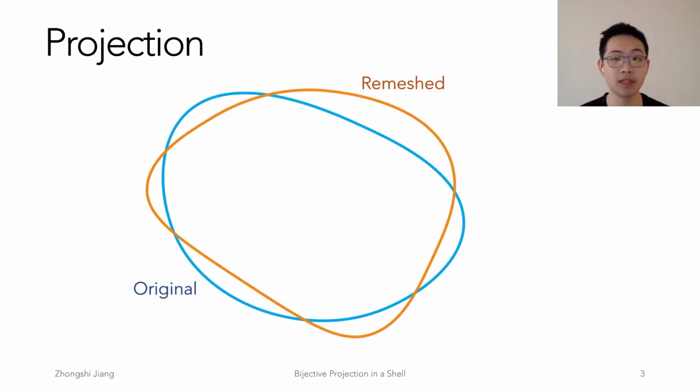The meshes approximate the same shape, so they should be close by in space. Therefore, our first attempt is to perform a closest point query. For each point on the original mesh, find which point is the closest on the new one. For smooth surfaces, this corresponds to Euclidean or orthogonal projection. More specifically, if you trace along the surface normal, then it might hit another mesh if they are close by and smooth enough.